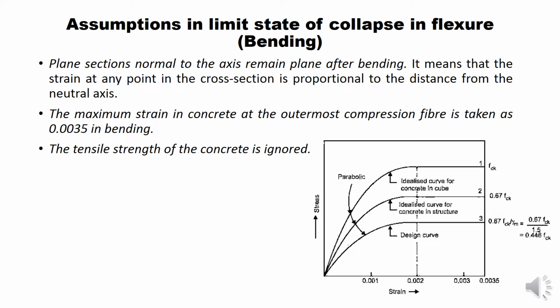The stress block may be assumed to be a rectangle. What is a stress block? The stress block may be assumed to be a rectangle, trapezoid, parabola or any other shape, which results in prediction of strength in substantial agreement with the results of tests.